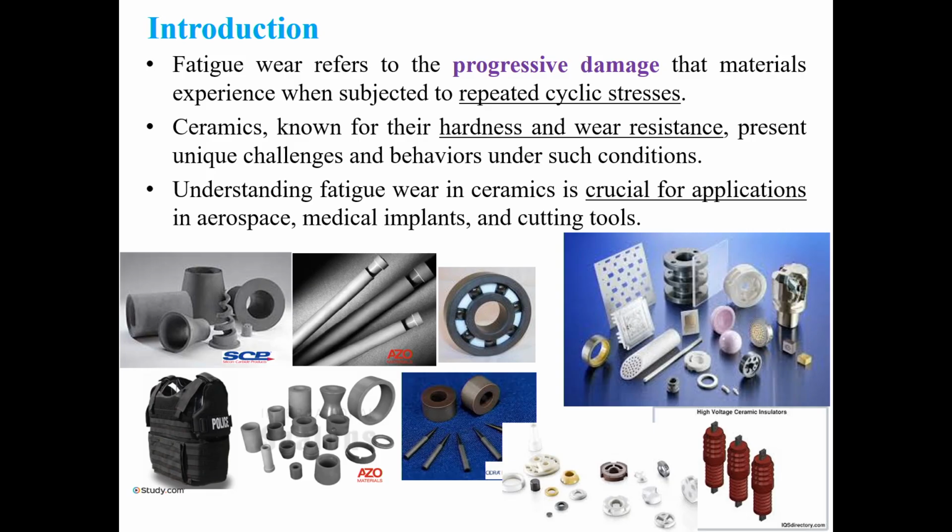In ceramic materials, particularly for fatigue wear, progressive damage leads to the development of debris, and that debris leads to further fracture and wear of the material. In the case of ceramics, the most important point is that they have been chosen because they are hard, and at the same time they are wear resistant and corrosion resistant.